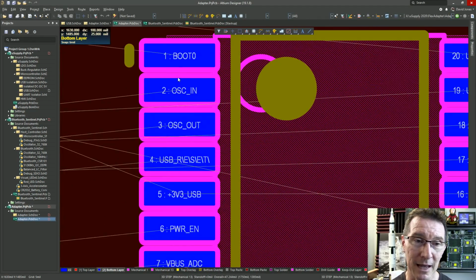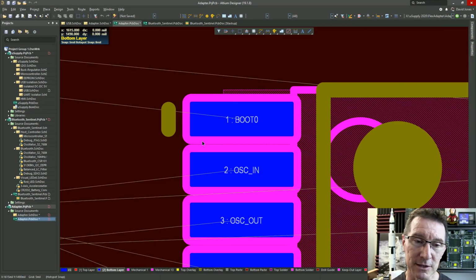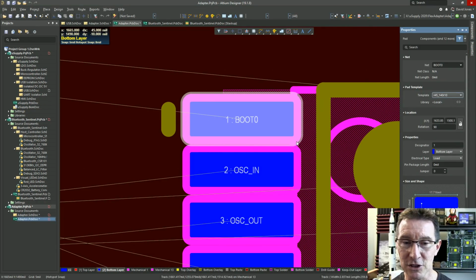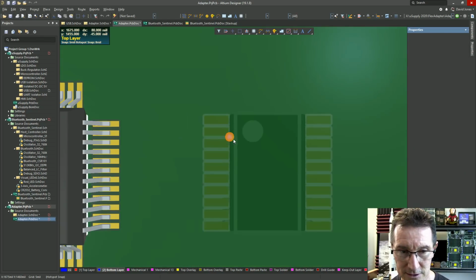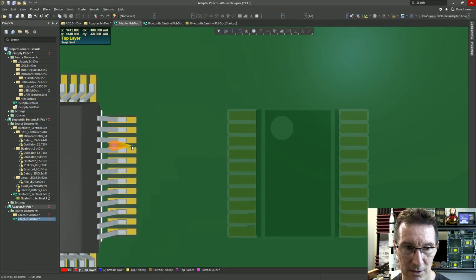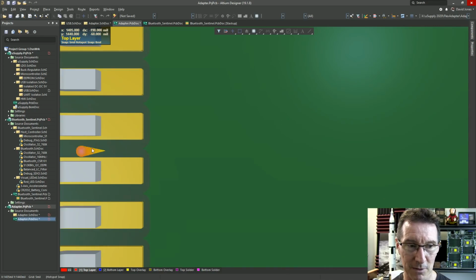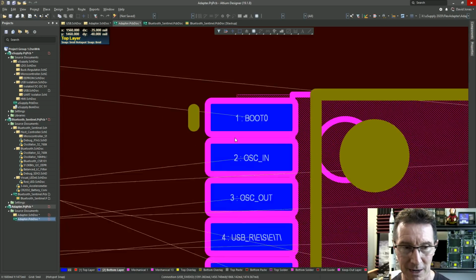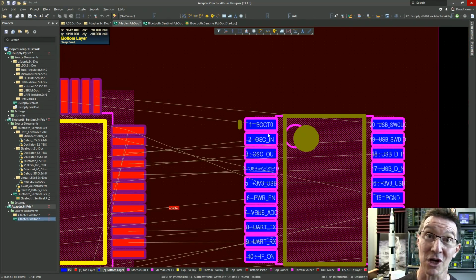So what we need to do now is go in here. Geez, look at that expansion on those pads. That's touching. Look, there's no solder mask sliver. If we go into 3D view, look at this. There's no solder mask between pads there. You could easily bridge your solder out. So our solder mask expansion is too big, so we're going to have to change that.